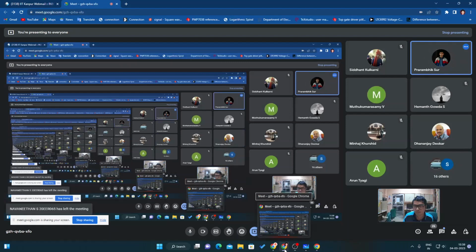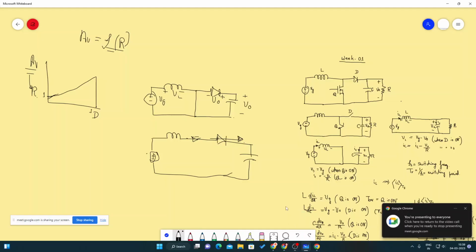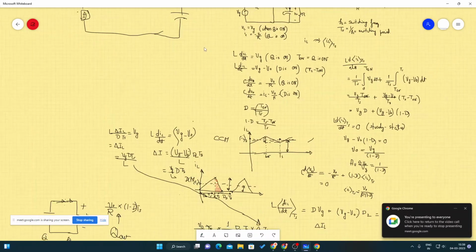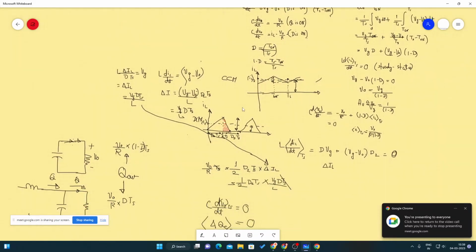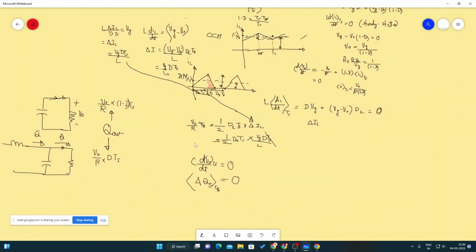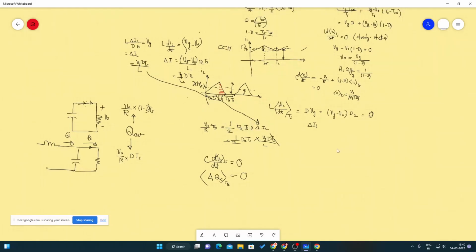Yeah, go ahead. Go to the voltage equation in DCM. You have to conclude that final equation. There itself, D and D2 are appearing, but the D3 portion of the total switching cycle is not appearing. Why is it? Okay. Because during D3 actually there is no voltage across the inductor.